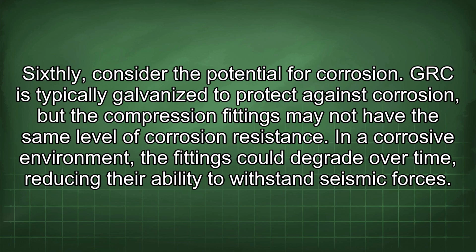Sixthly, consider the potential for corrosion. GRC is typically galvanized to protect against corrosion, but the compression fittings may not have the same level of corrosion resistance. In a corrosive environment, the fittings could degrade over time, reducing their ability to withstand seismic forces.